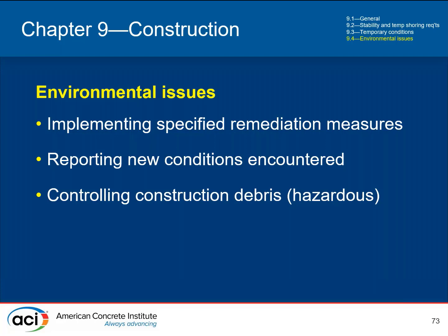That needs to be communicated as part of the construction documents. It's typically things like: they need to not disturb it and report it to the licensed design professional and to the owner, and then how to remediate it and who's responsible for remediating it can be decided at that time. It will be the owner's financial responsibility, but a decision needs to be made.